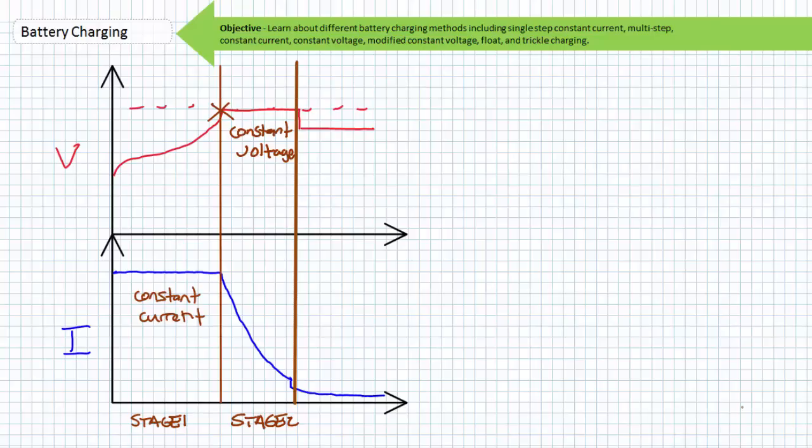For a typical lead-acid battery, this might be around 14.4 volts, although you need to verify this with the specific battery manufacturer. This constant voltage stage continues with decreasing current and provides saturation. This stage ends when current has decayed to a predetermined level on the order of 0.1 C20. At this point, another constant voltage stage begins with a float value sufficient to complete the charge and compensate for the loss caused by self-discharge.